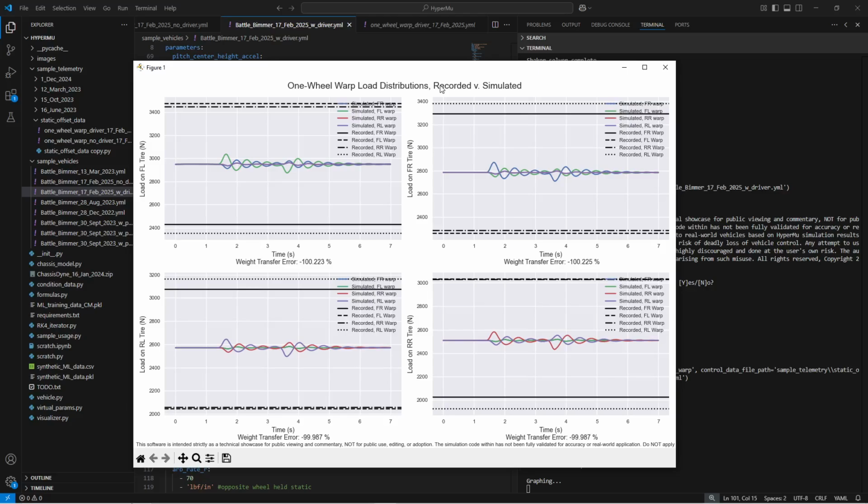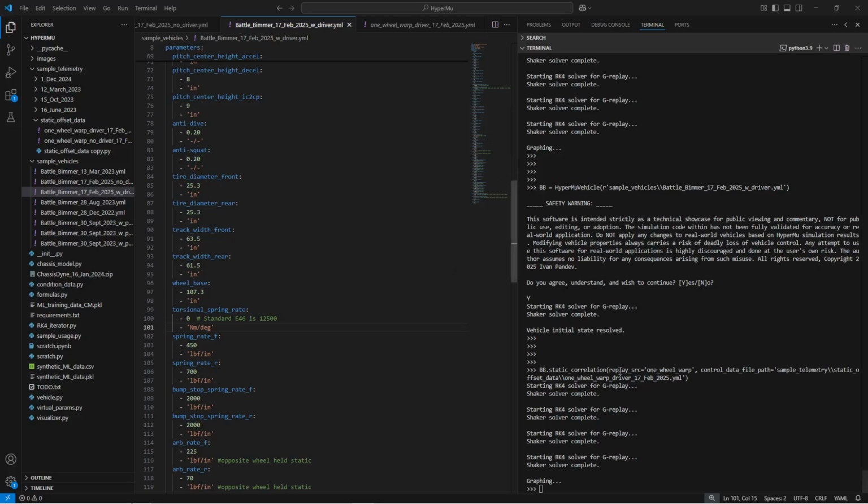The results confirm our intuition, showing no weight transfer on any tire when the torsional stiffness is set to 0. You can see some signal as the tires respond to the shaker floor moving into position, but it settles to the original value. While I wish that the errors in the conventional loading case were smaller, it's always cool to see the model behave correctly, even in theoretical, goofy scenarios which the simulator wasn't even designed for. The point being, with a more accurate torsional stiffness value, I would expect the error to be significantly better.